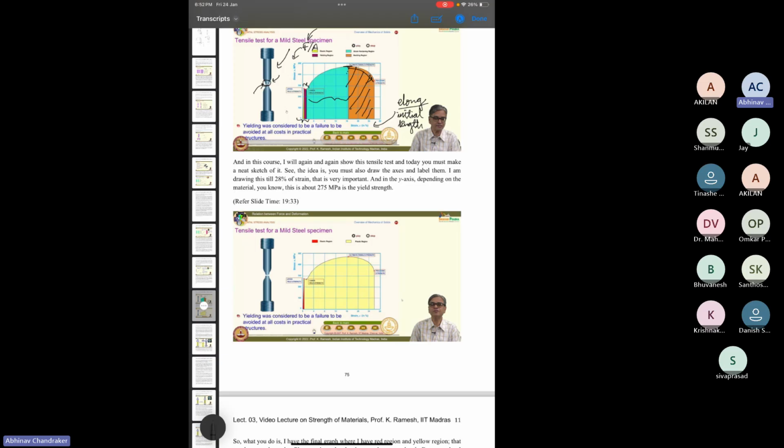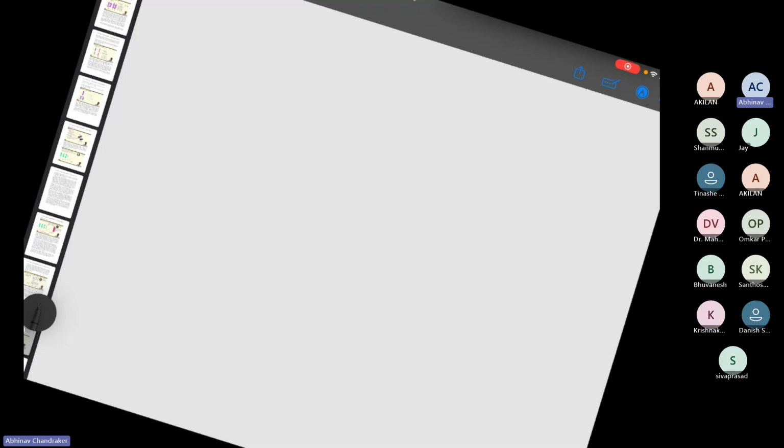If you still have doubts, you can share with me the link to whatever resource you used to look up this, and I can maybe help you with it. But in general, the differences are due to variations in the defects in the material or some changes between two different specimens. It is not always totally homogeneous. There will be some small differences. If you plot for multiple specimens, it might be something like this. Usually the ductility percentage changes a little, but the strength is almost the same. So even for experimental purposes, we never use just one single specimen. We use at least three different specimens of the same material to get some representative results.